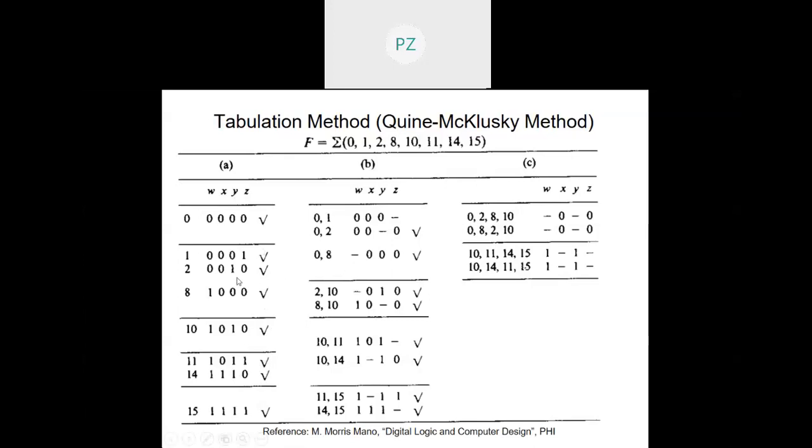So let us consider these two groups. So combination of 1 and 10 cannot be done. Why? Because they are varying in more than one place. I can make out from here itself. This is 1 0 and this is 0 1. So even if I consider the other places, it is varying in more than one place. So they cannot be combined. So that is why I haven't written 1 and 10 here.